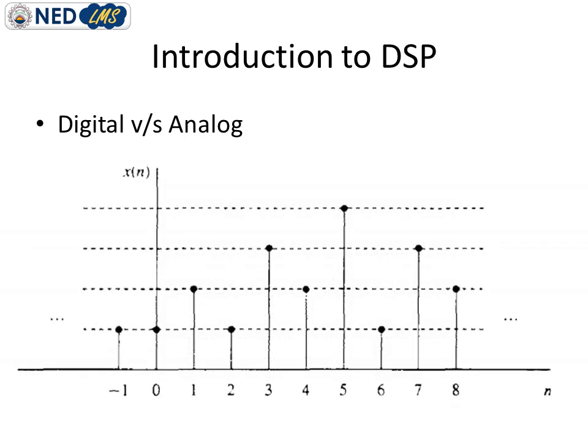So generally speaking, initially we have an analog signal. From that analog signal we obtain discrete time signal by sampling the time axis, which is the x-axis, and if we sample the y-axis also, we will get a digital signal.